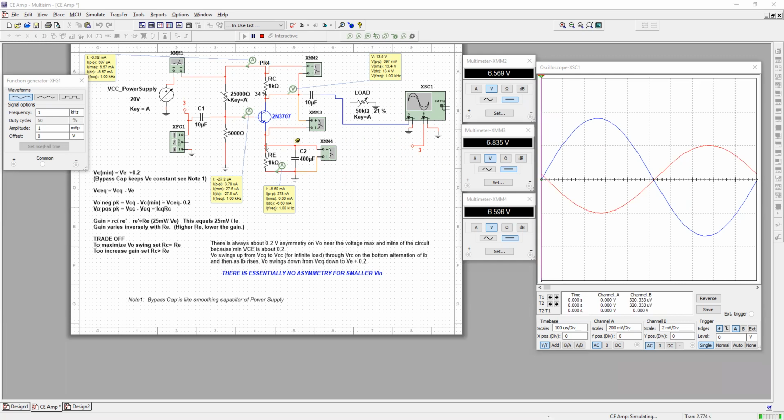Likewise, all of that ripple is going to be felt at the capacitor. And this is going to act like a wire for the AC voltage, just for the ripple. Now, it's going to maintain a VE base voltage, and it's going to fluctuate above and below the VE average voltage at the capacitor.